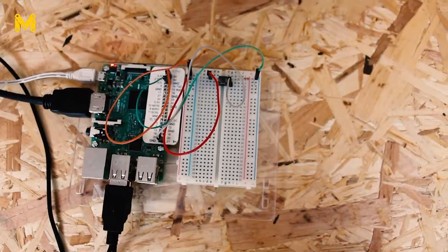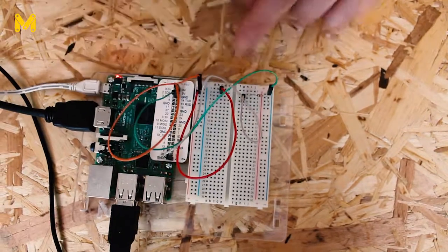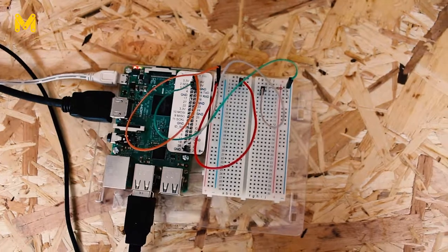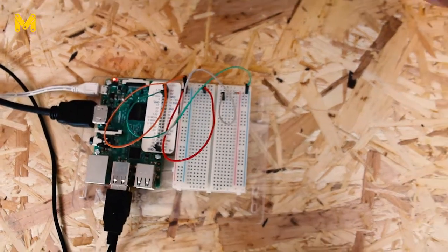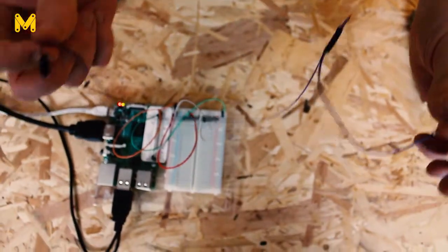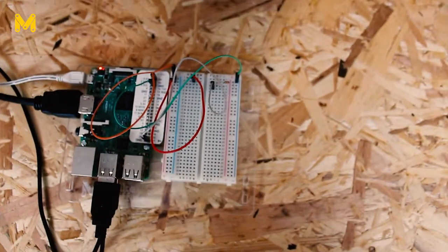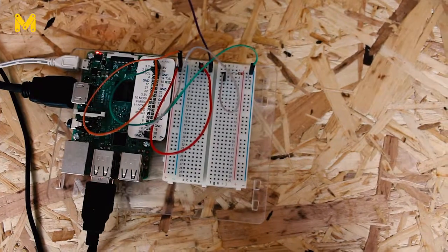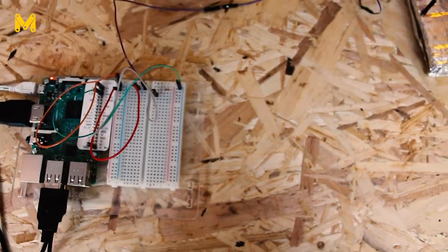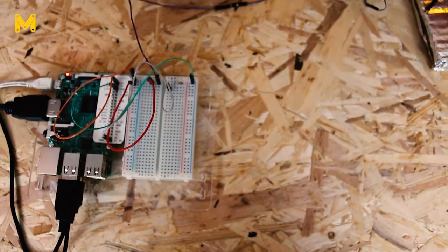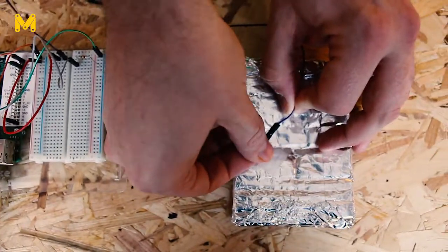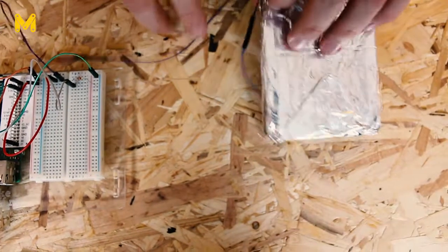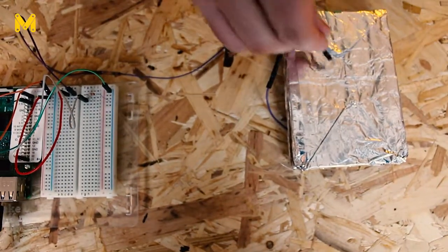Now the first thing we're going to do is take this switch out of our circuit, and replace it with some wires. Now all I've done here is daisy chain two male to female wires together with a male to male jumper wire, and I'm going to put that into there. And then I'm going to take this end and sellotape it to the top of my pressure pad. Then I'm going to turn the pressure pad over because I want to put another one on this side.